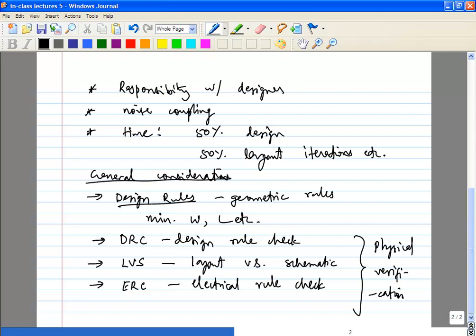Those will typically be larger. So the minimum length on those may be, let's say, 0.25 microns, 250 nanometers, and the corresponding oxide thickness will be thicker. The corresponding voltage supply will be higher for those transistors. For the 0.13 micron transistor, we are using 1.2 volts. The other one may be, let's say, 2.5 volts or 2 volts. Okay, what happens if you connect a 2 volt supply by mistake to a 1.2 volt transistor?